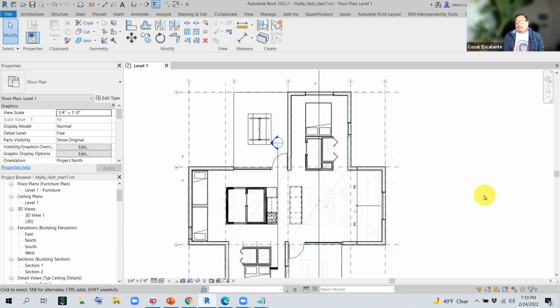First, you need to select or define a light source. The light source could be internal, and we need to place luminaires. The luminaires need to have photometrics associated with them. And then you need to connect the project with a site location in the world so that we can get an accurate reading from the sun. I'm going to show you how to do that.